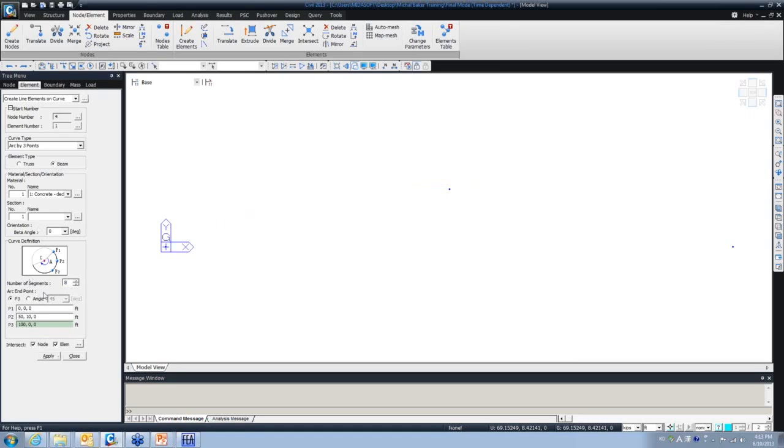So let me show you. If I change it to 40 elements, what's going to happen from here to here to here? You see it gives us smaller dimension beams, and then all the nodes would correspond to the geometry that you have. So all these are available now also for you.